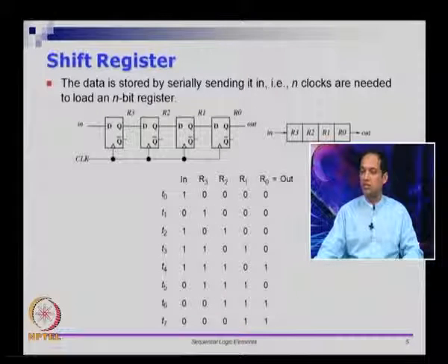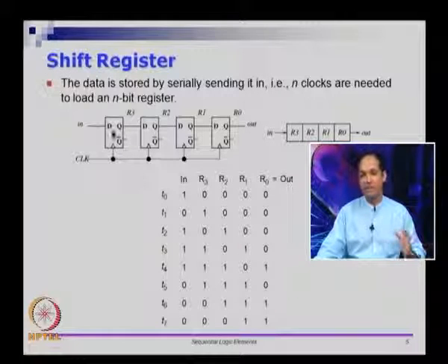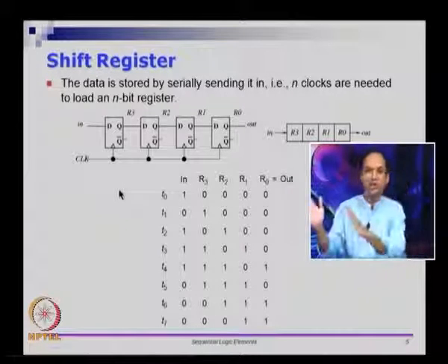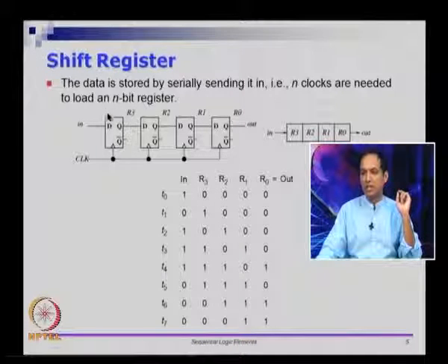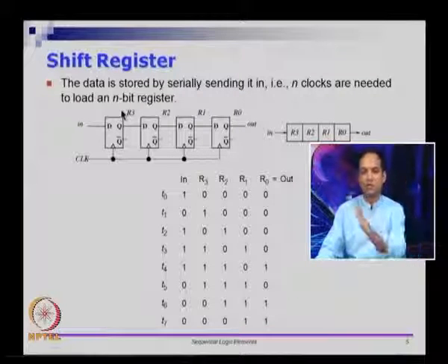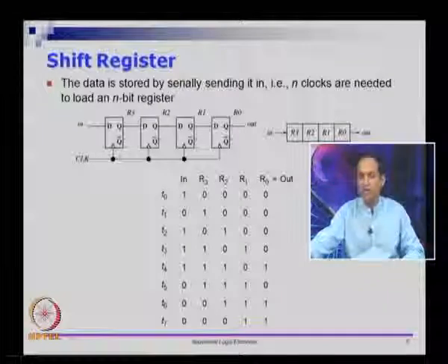So this is the picture that represents the shift register. We have one input bit and one output bit. I hope that this is clear to you. What is happening in this case is it's shifting all the bits to the right. So we are going from this side to this side. We will call this flip flop F3 and this is F0. So it's shifting bits from left to right. This is called a right shift register to be specific.